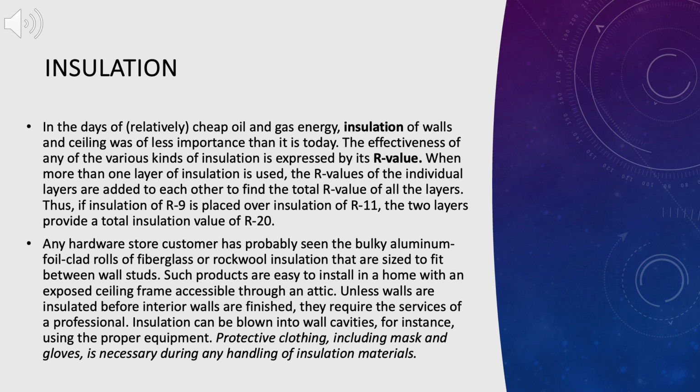Any hardware store customer has probably seen the bulky aluminum foil-clad rolls of fiberglass or rock wool insulation that are sized to fit between wall studs. Such products are easy to install in a home with an exposed ceiling frame accessible through an attic. Unless walls are insulated before interior walls are finished, they require the services of a professional. Insulation can be blown into wall cavities, for instance, using the proper equipment. Protective clothing, including mask and gloves, is necessary during any handling of insulation materials.